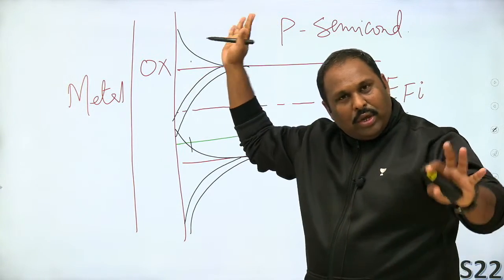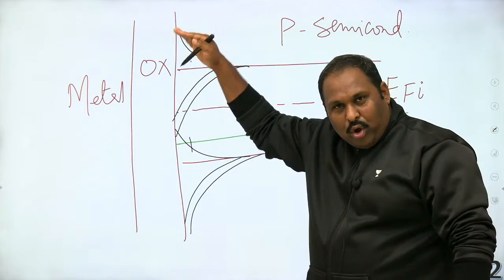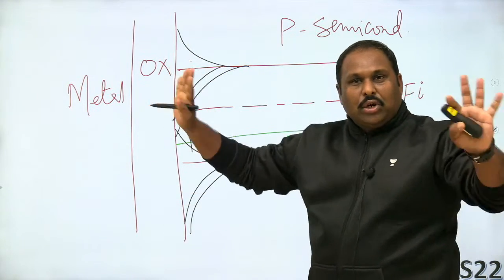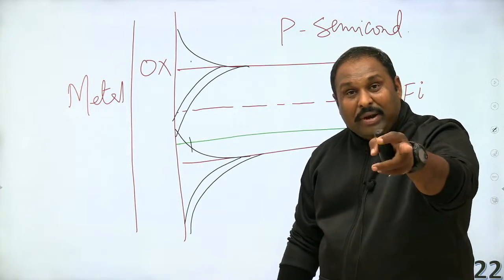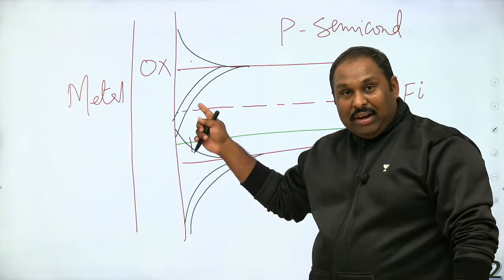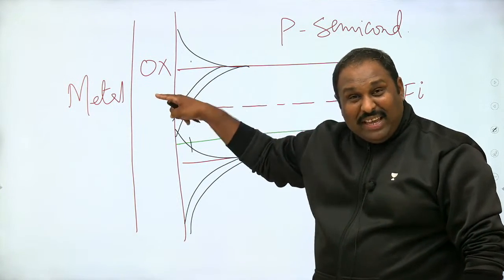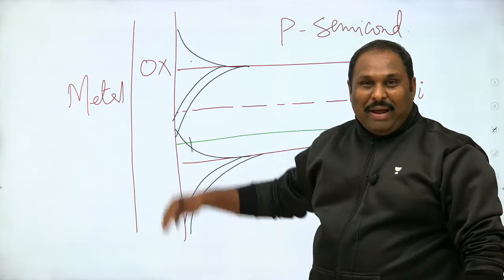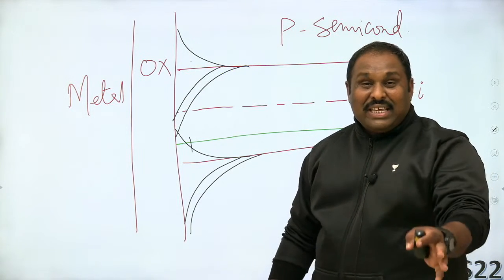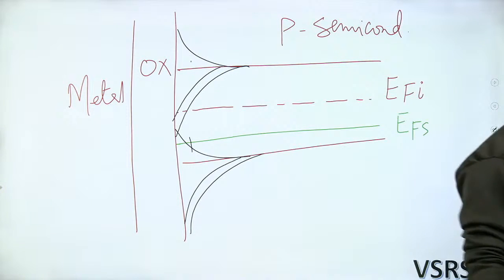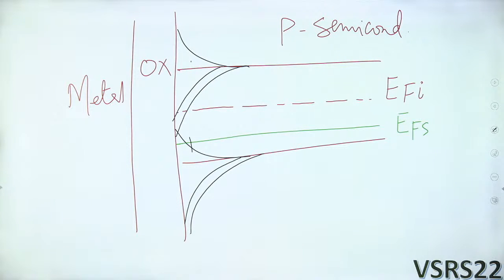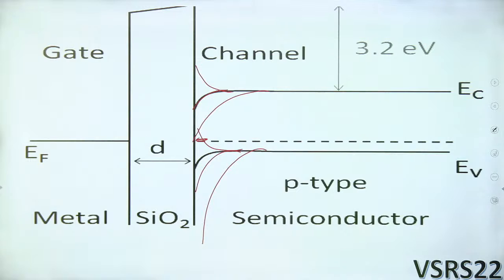Whether the substrate is P or N, it is important to see whether the levels overall are going down or up. And the difference between depletion and inversion is that the levels shift so heavily that the Fermi level comes to the conduction band. Then we say N channel inversion took place. So that's where you identify it.